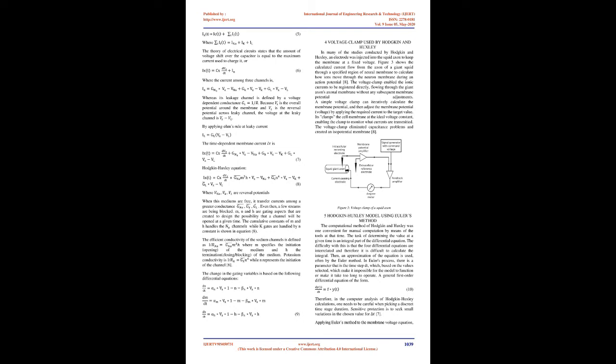The semi-permeable cellular membrane separates the interior of the cell from the exterior. Figure 2, simplified equivalent circuit for a small section of the giant squid axon. In Figure 2, the input current I(t) is transferred through the cell, either providing charge to the capacitance or leaking along the cell membrane channels. A resistor represents each type of channel. The unspecific channel has a resistance to leakage, a resistance to the sodium channel, and a resistance to the potassium channel.